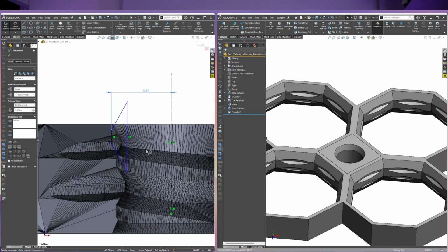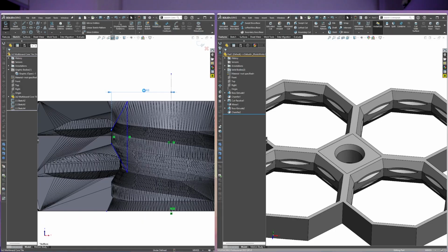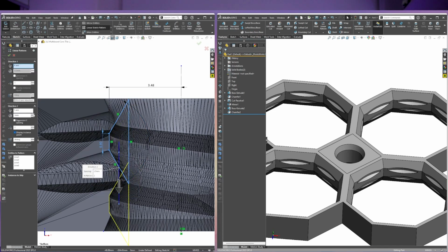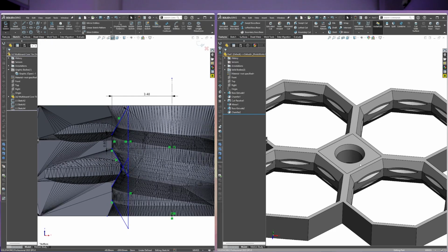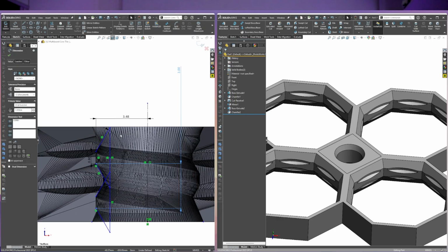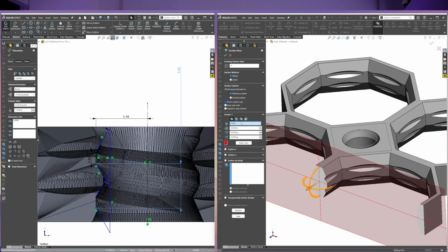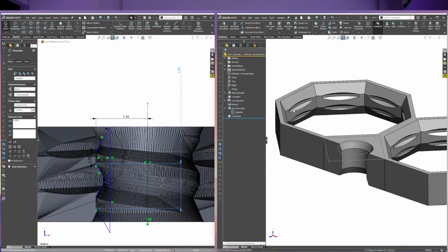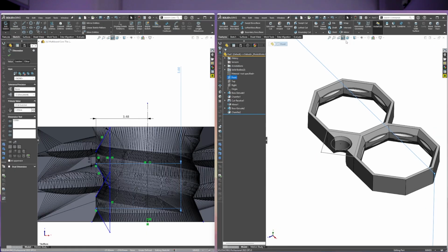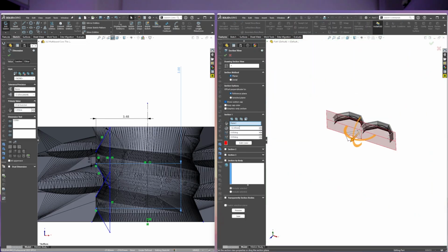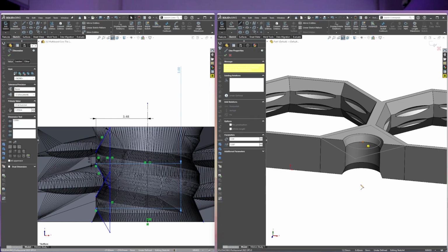Here, I'm sketching one profile. I'm using the center point for that circular area. And again, I'm assuming that a lot of the dimensions are going to be round numbered dimensions. Okay, so where I see a dimension, I'll sketch the line, I'll add it, and I'll get that as close as I can to the actual points. I'll then dimension it, and if the dimension said like 3.47 millimeters, I'm rounding up to 3.5. So with a thread, recreating a thread here, the main thing to work out is the pitch of the thread.